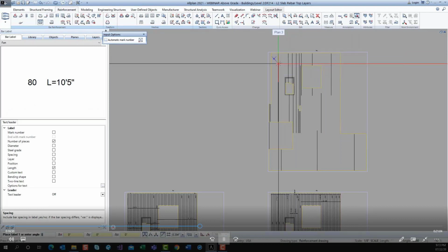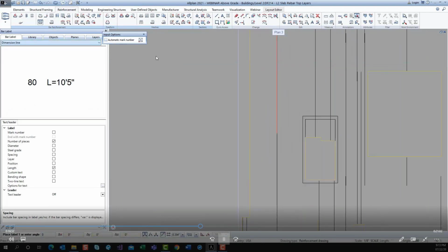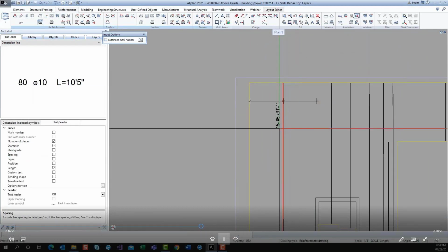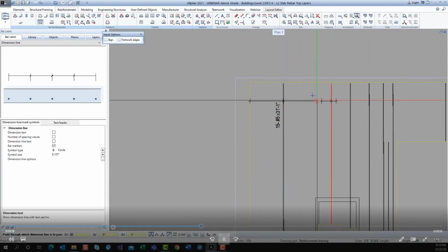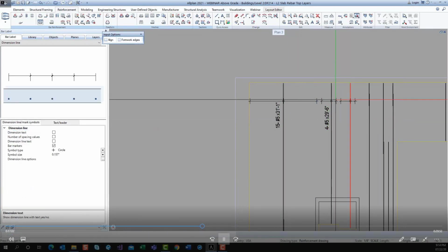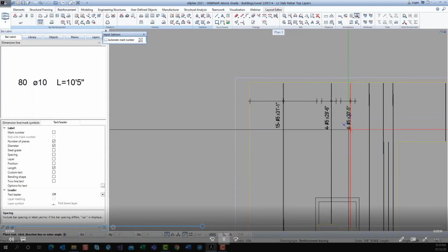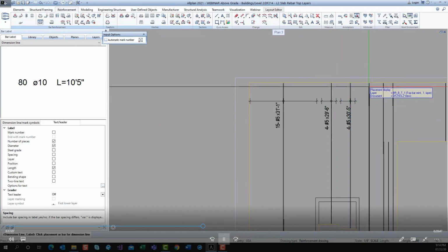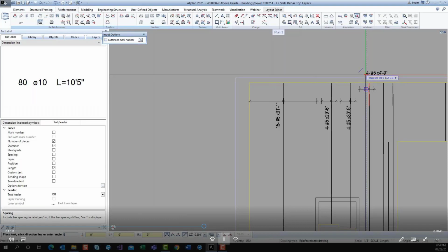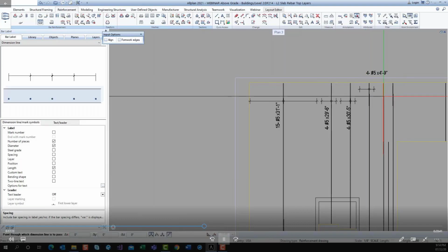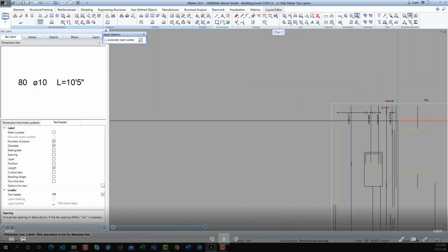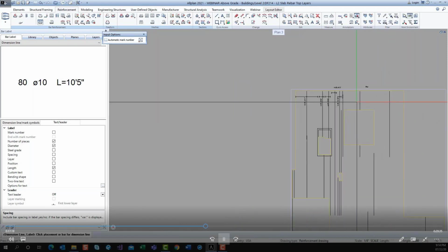And again, what I'm showing you here is that after the fact, you don't have to follow through your tool to apply your dimension. What if I just want to do it afterwards and align the tool quicker? You can do it after the fact. As we've seen with other software, where start to finish you have to do this, label the bar, place the bar, we allow you to do all your placing and label and dimension how you want afterwards. And we don't define what that label needs to look like in each one of those views at the time you're creating your bar.